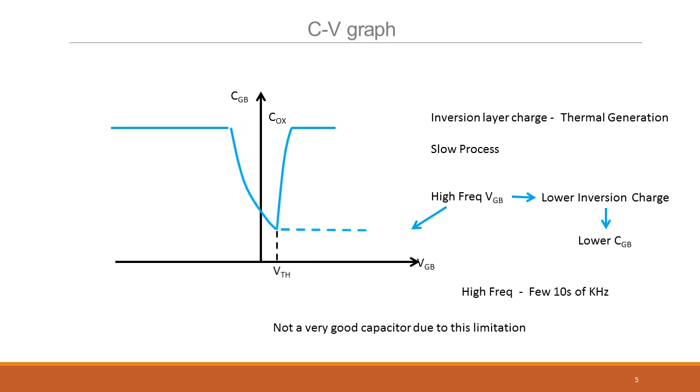But before we do that, we said VGB is greater than 0. We drew a thing at VGB equal to 0, but that's exactly not true. There's something called a flat band voltage. When VGB is less than the flat band voltage, it is Cox. Once it crosses the flat band voltage, it follows the depletion region, and once it hits the inversion voltage, it starts increasing back again.